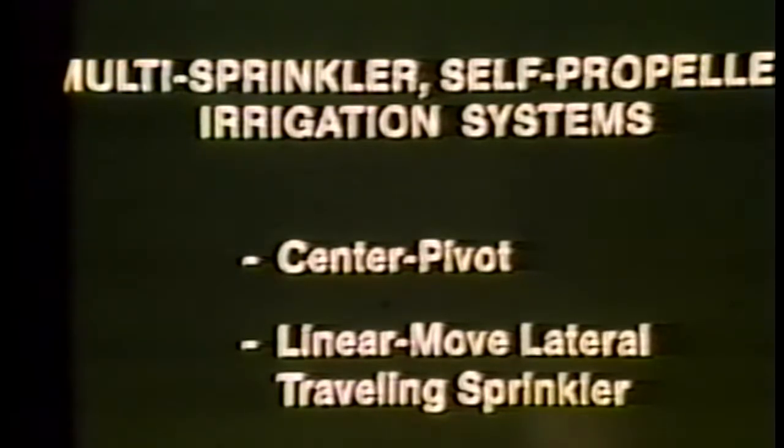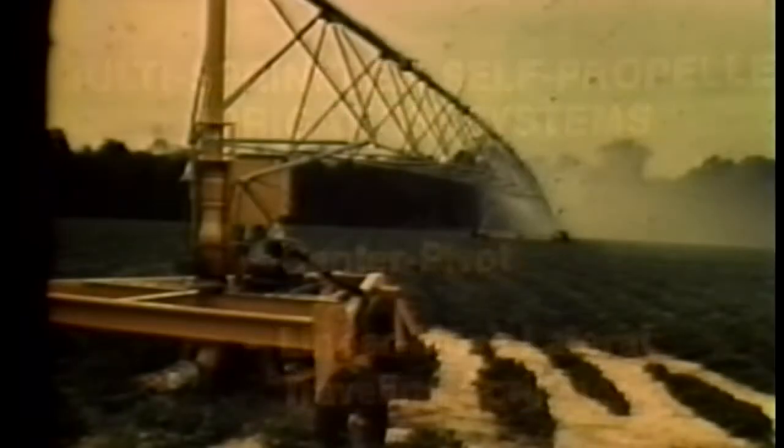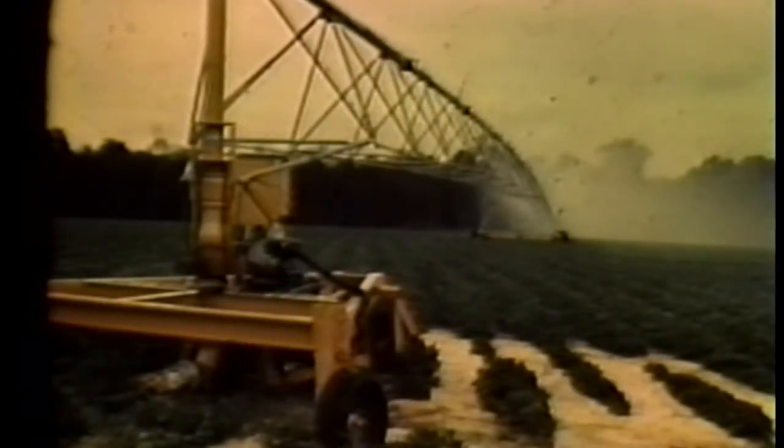The continuous move laterals are self-propelled irrigation systems that represent a further development in sprinkler systems directed toward reducing the amount of labor required to operate a system. These systems are discussed as center pivot, linear move lateral, and traveling sprinkler. The center pivot type of system has a single lateral which rotates continuously about a center pivot. The lateral is usually made of painted or galvanized steel pipe connected by flexible couplings. It uses small or medium-sized sprinklers along the lateral and larger nozzles at the outer end for equal distribution of water.